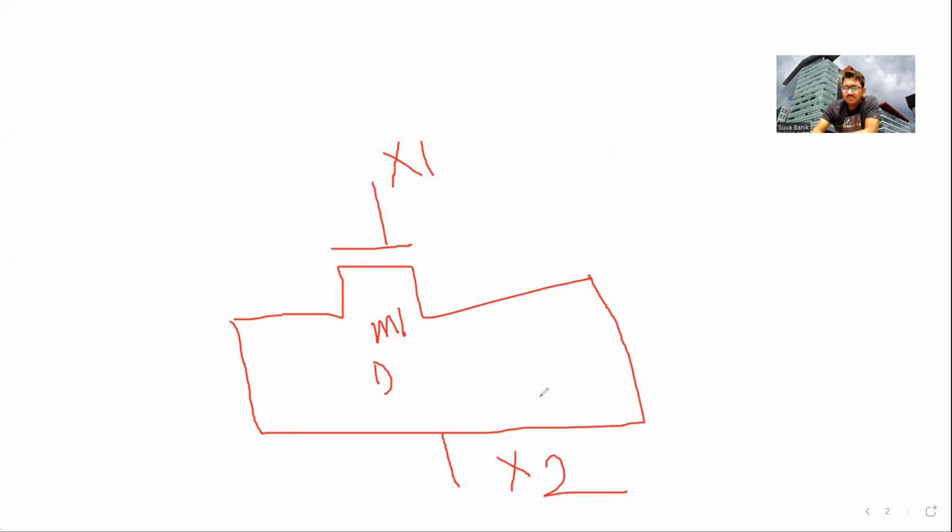Never do this. If you do that, basically this transistor works like a capacitor, which slows my circuit, and is responsible for my RC delay and lots of different things. But never do that. In a real circuit there is a lot of parasitic capacitance as well as resistance. Among these, if I also add one external capacitor in the left or right corner, then it would be a problem for me. So never do this type of connection.